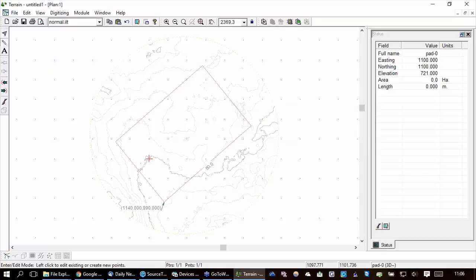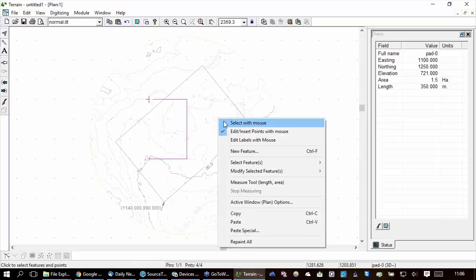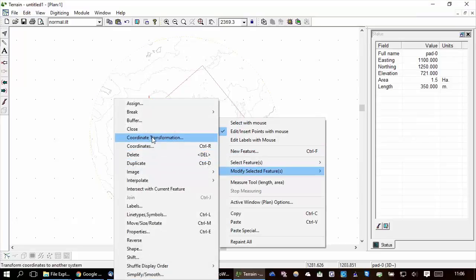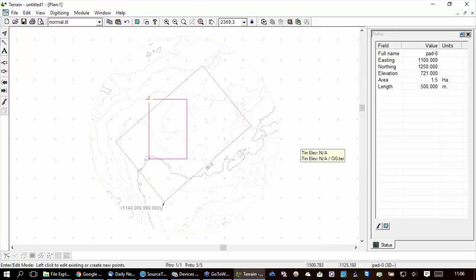Okay, and I'll draw that. There's my snap to grid. Go over to here. I've just created a 100-meter side. Okay, that seems reasonable. And up to there, over to there, down to there. Oops. Actually, I'll just use the close function. Okay, there's a rectangle. Now, notice that all the points are at elevation 721, so that's good. It's flat.